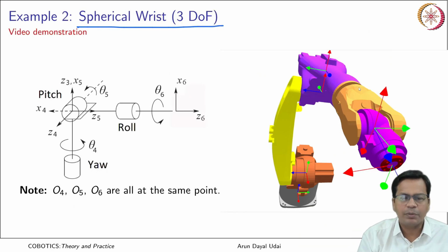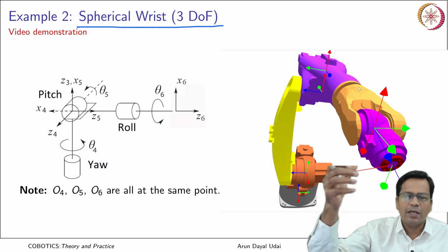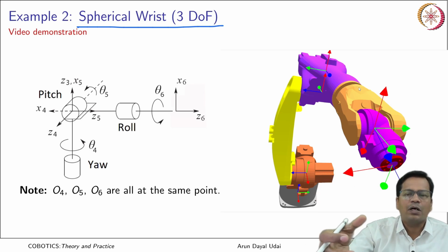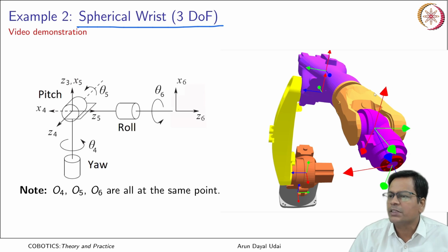The next one would be to orient it. Now I have reached there, I'll orient it, align it with the object and do some valuable work. To align it, you need further 3 rotations, as you have seen in Euler angle systems earlier. So this is one of them. It is the roll pitch yaw system. So you see what it does basically.